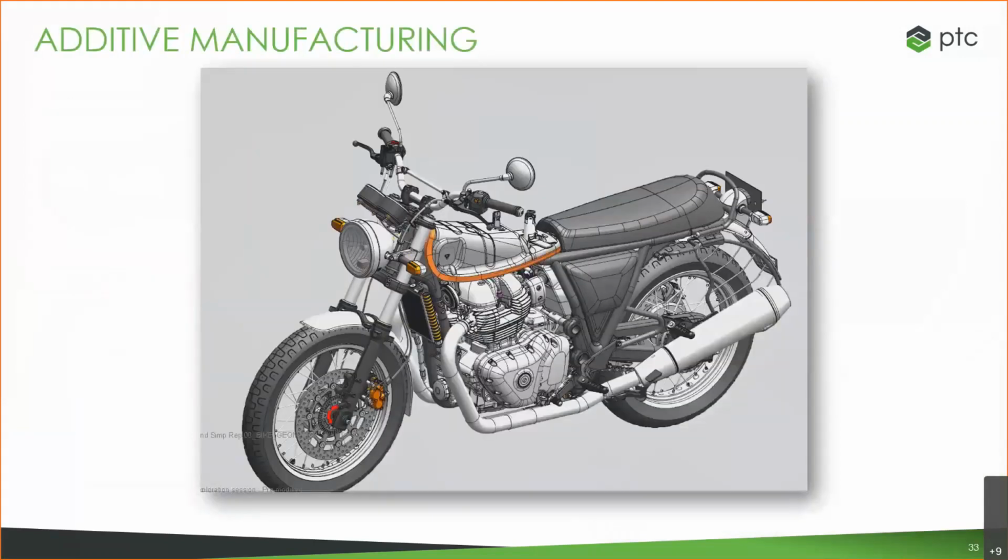Additive manufacturing is another one. Again, as simple as the sheet metal things were to do, right? It does some of the work for you because it knows what a flange is, and then you design, right? What's the angle going to be and how thick is it? Additive manufacturing is very similar. You can add very complicated geometries like lattices, but do it very simply by just defining a couple of parameters as if it was a single feature. So cell size, cell type, right? Cross section, wall thickness, whatever it might be.